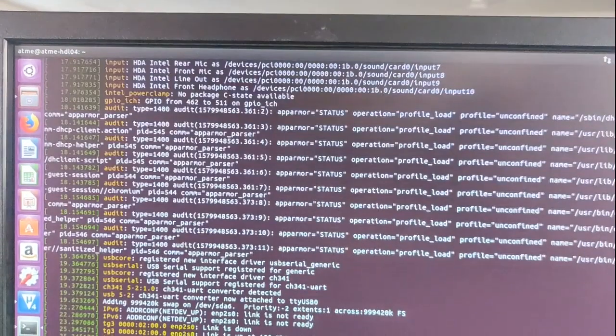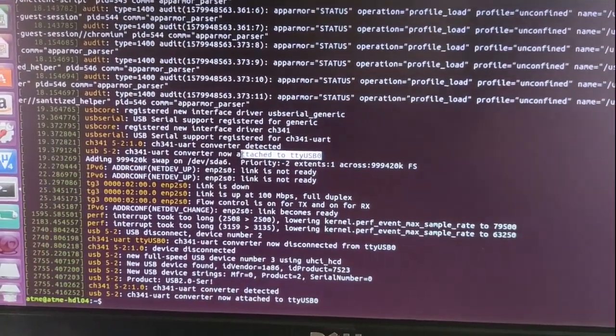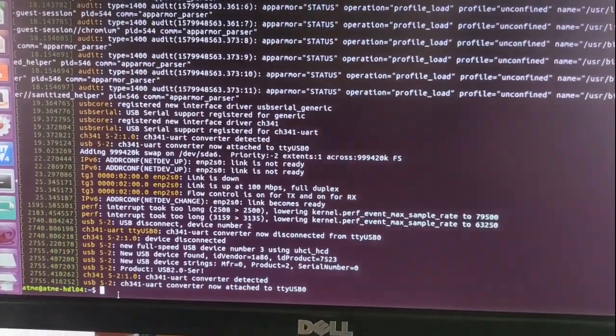I hope you understood the program flow of the UART program, in order to display hello world in the hyperterminal. So now I will show you how to download the program and how to execute it with a hyperterminal. So the first command, as we did in the previous example, is dmesg in order to test the device ID. So you can observe here that ttyUSB0 is the device ID which is generated by the system.